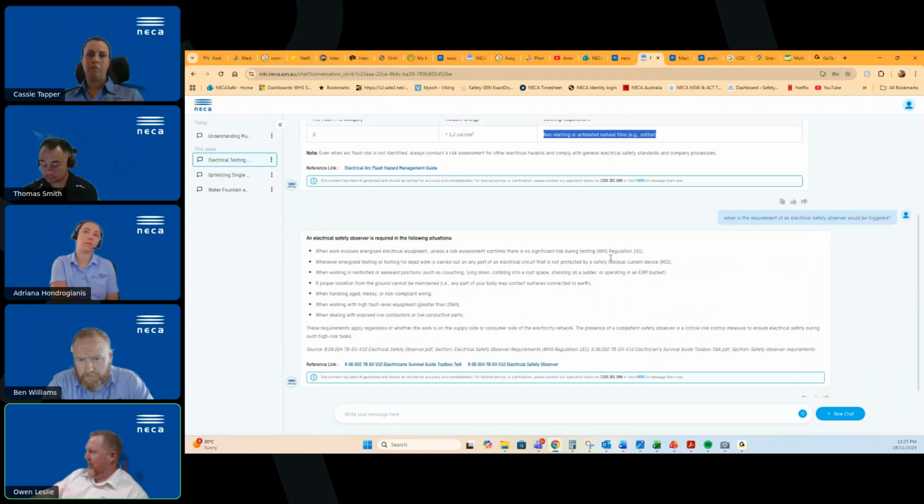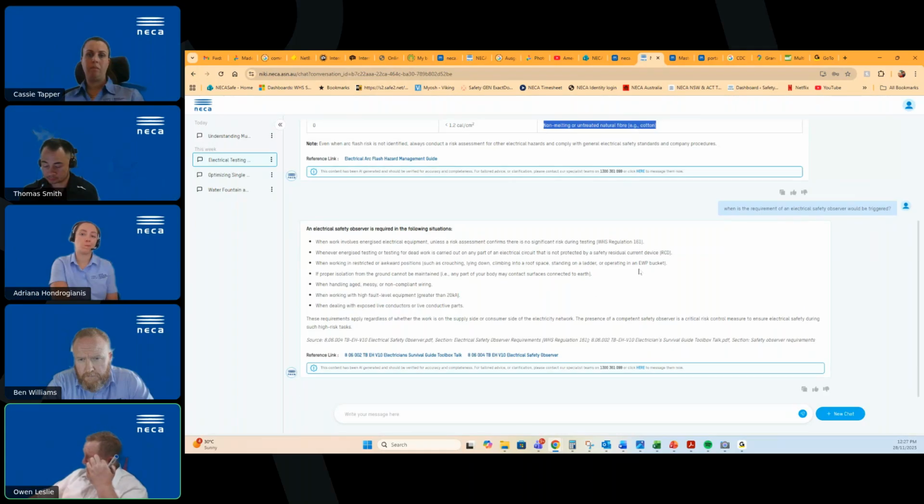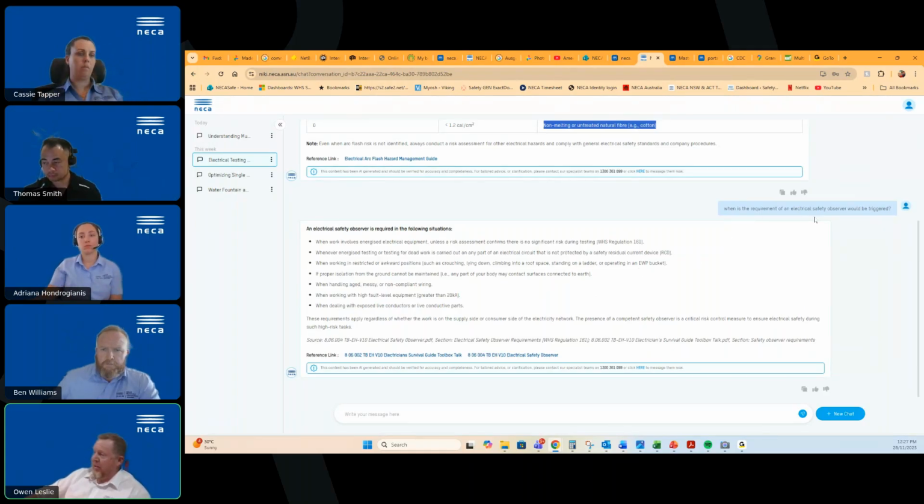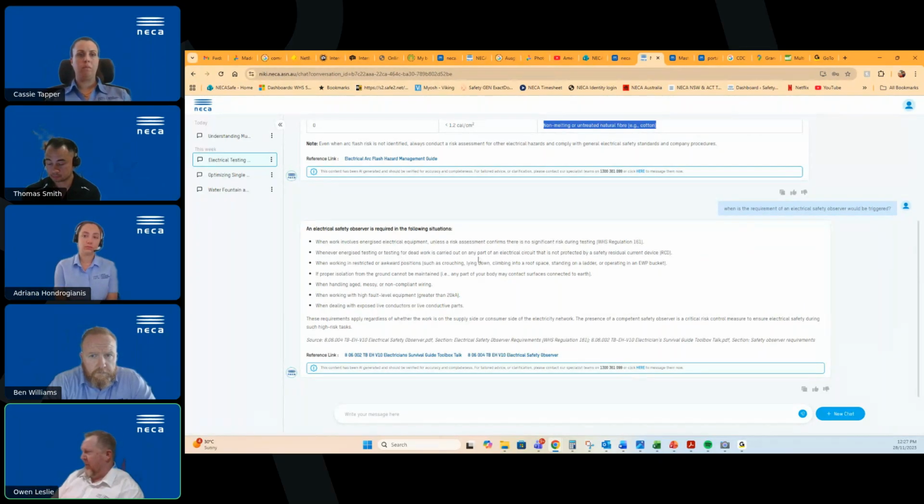So once again, I asked it a question: when is the requirement for an electrical safety observer triggered? And it gave me a pretty good response here in Nikki as well. When work involves energized electrical equipment, unless the risk assessment confirms there's no significant risk during testing, Regulation 161. When energized or testing for dead work is carried out as part of an electrical circuit that's not protected by a safety residual current device.